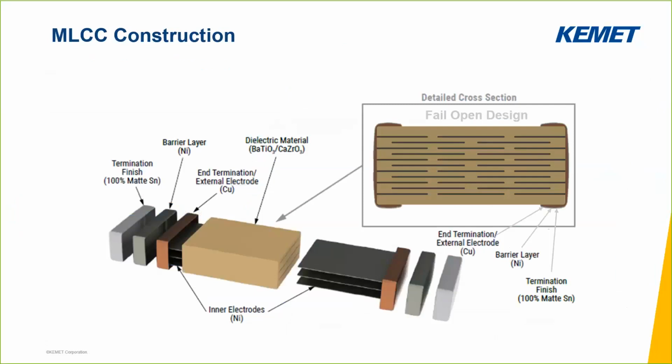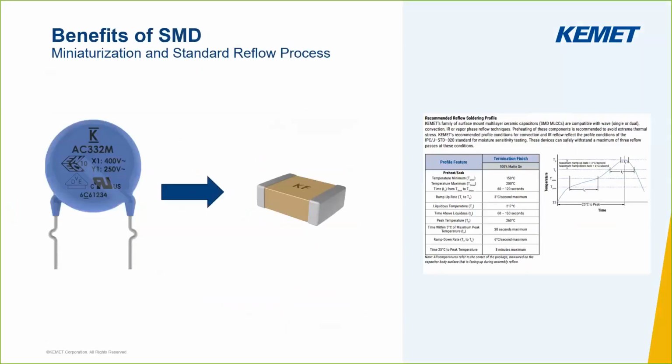Now, because these are very high voltage capacitors, we employ a serial electrode design, which is normally fail open. There's a lot of concerns about flex cracks out there. These are normally fail open devices, which is desired in an environment where flex crack is a concern. MLC safety certified capacitors provide a much smaller form factor than leaded disk capacitors, and also can be surface mounted using industry standard reflow profiles.